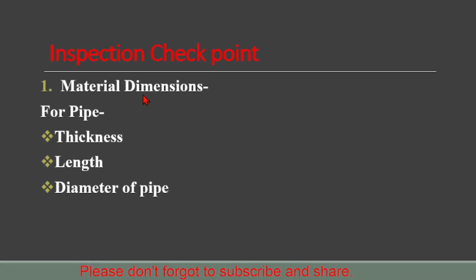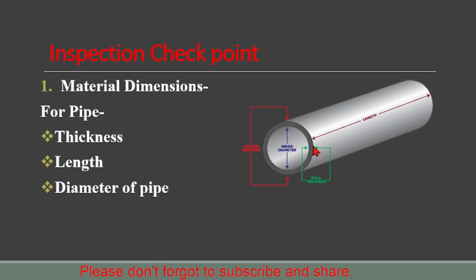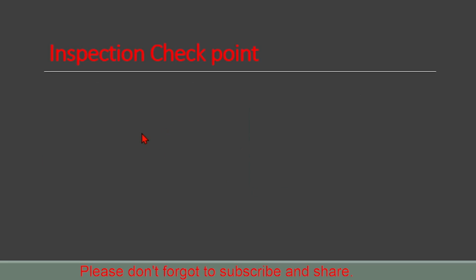Then another point is material dimension for pipe. When we go for checking the pipe, what are the things we have to check? Thickness, length and diameter of pipe. So we can see here is the pipe, same things: whatever we ordered, as per order this pipe has come or not. So thickness we have to check, then wall thickness, that whatever we call for pipe is schedule. Then diameter of the pipe, inside diameter, outside diameter, and length. So these are the things we have to check dimension-wise for pipes during incoming inspection.